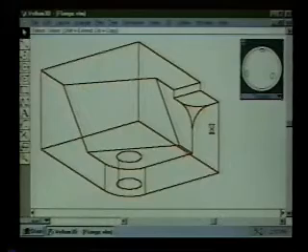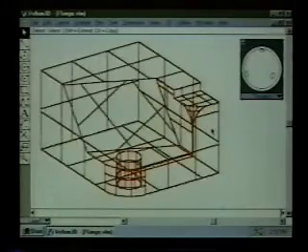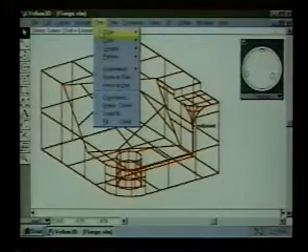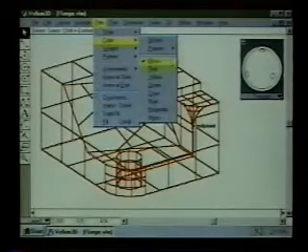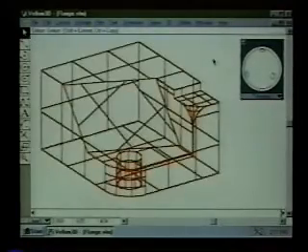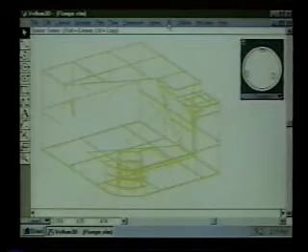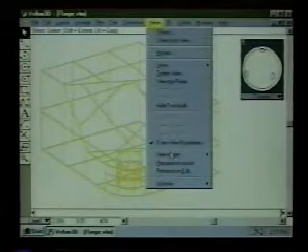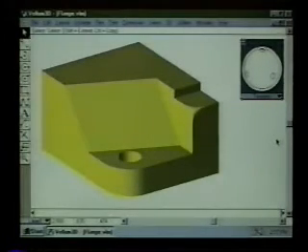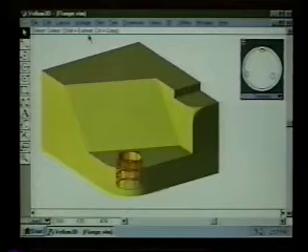The nice thing about the auto surface command is that it interprets your model and automatically places surfaces on all the right locations. So if I change the color of this object to something like yellow, for example, it will make yellow lines, but I can go in and change the viewing type to a shaded object, and we get a solid looking color shaded object. Okay, but now I'm going to go ahead and go on with this.